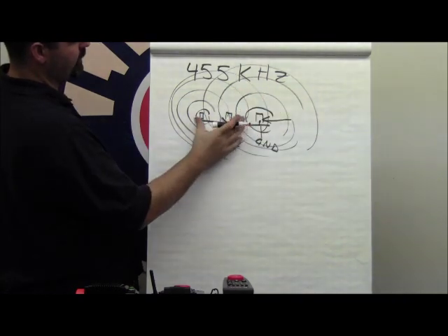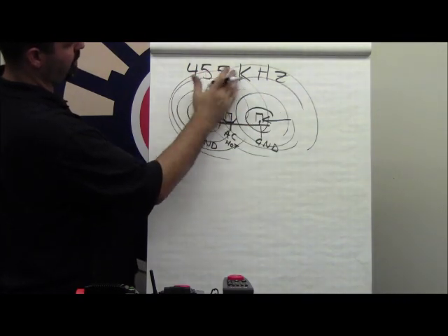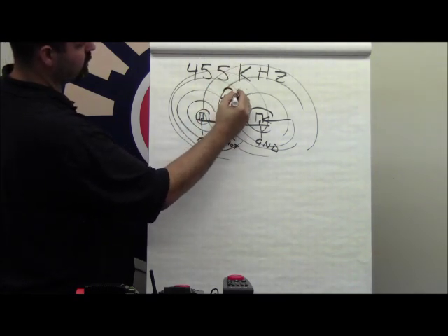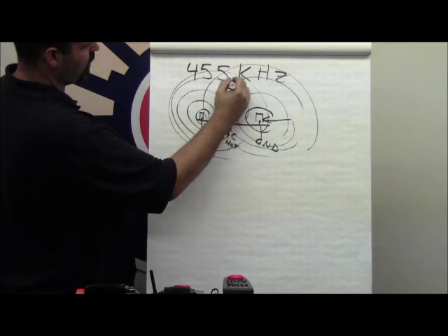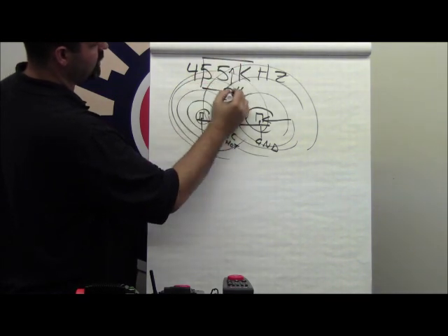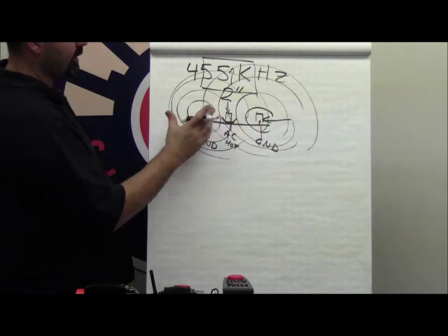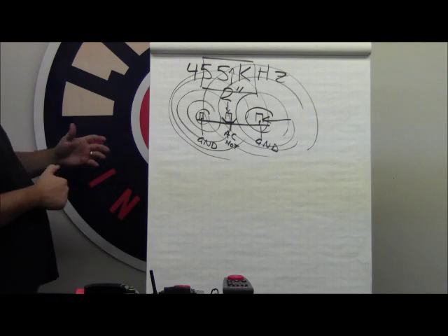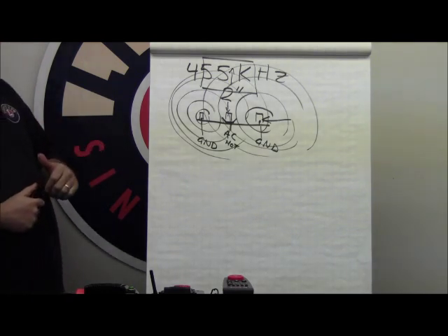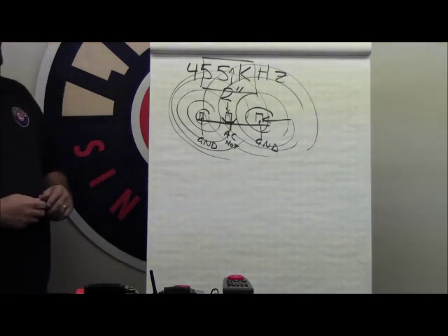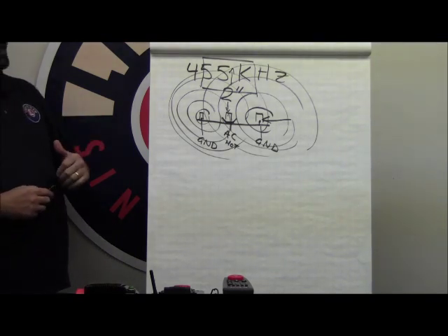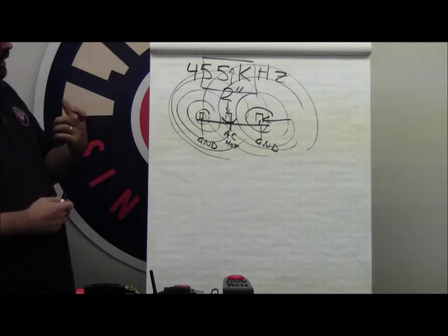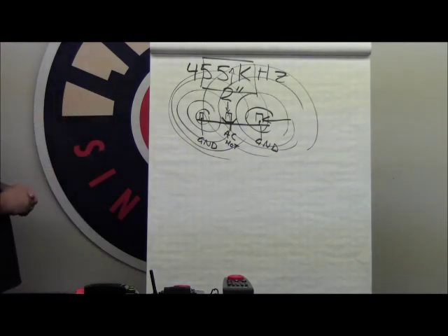As these signals are broadcast, you'll notice that the crosshatch up here on the track itself typically occurs about 2 inches from the top of the center rail to the strongest concentration of signal being broadcast through the air. On all of your Lionel locomotives, such as steam locomotives, the handrails function as the antennas. On your diesel locomotives with plastic shells, you have a metal antenna right underneath the roof of the plastic diesel.